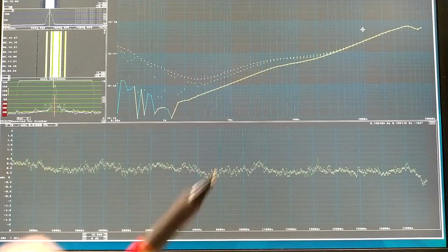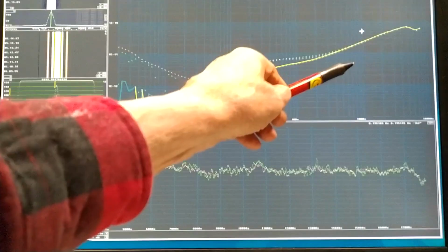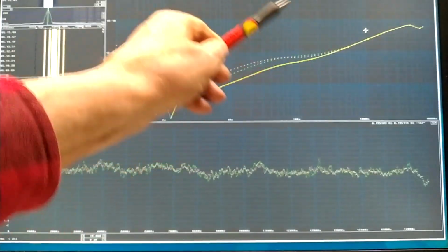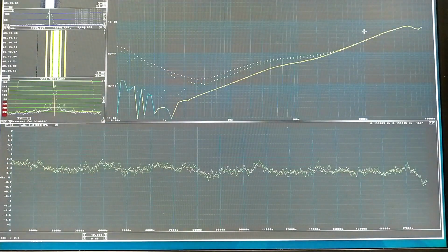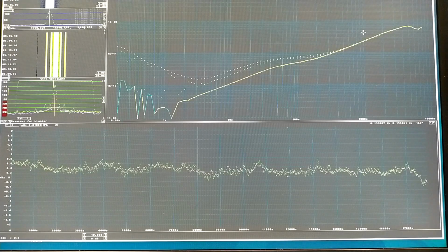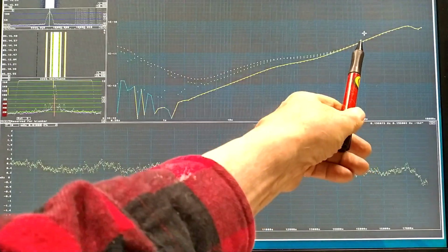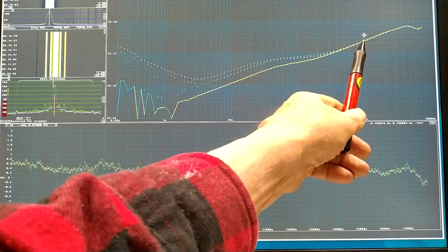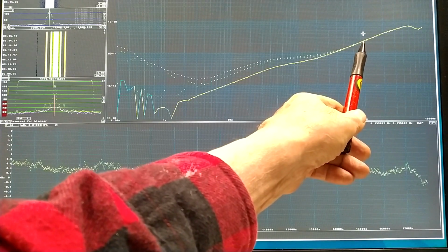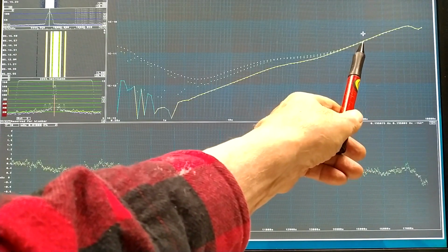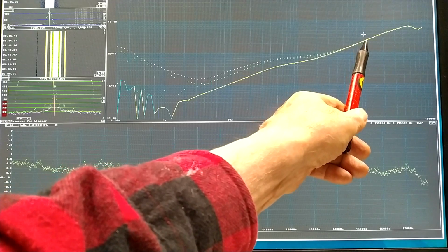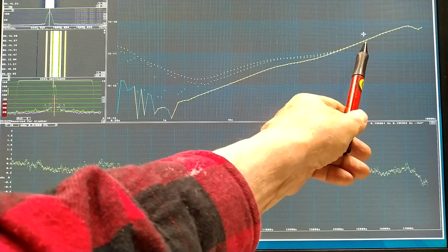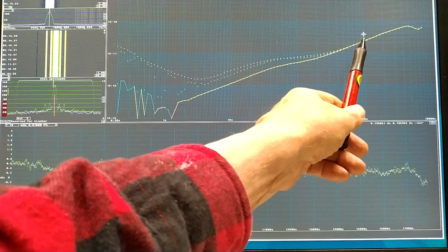The Allan deviation you can see here at 1000 seconds says 2.27 times 10 to minus 11. That should be the properties of the oscillator, because here red and green are in the same place, because that is the performance of the rubidium oscillator. And at 1000 seconds that is very good. So the trace here is my test object.